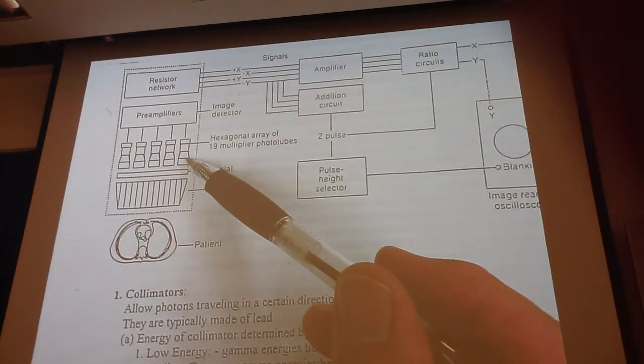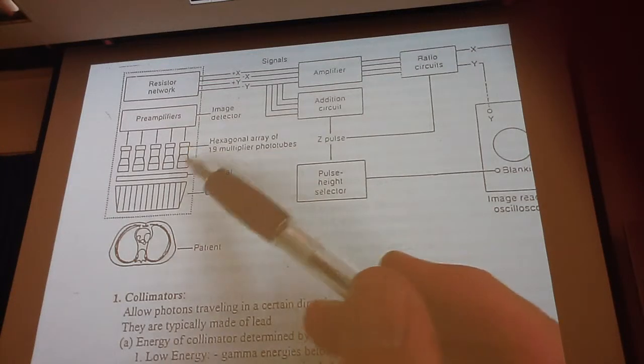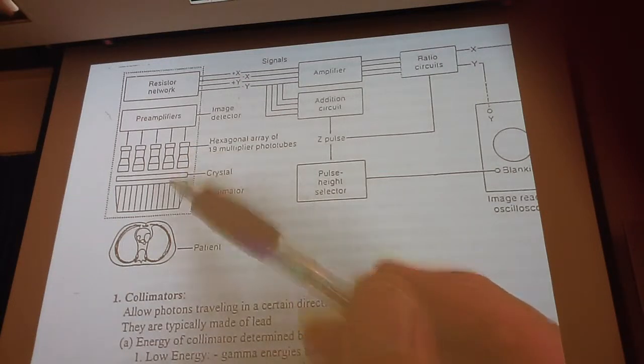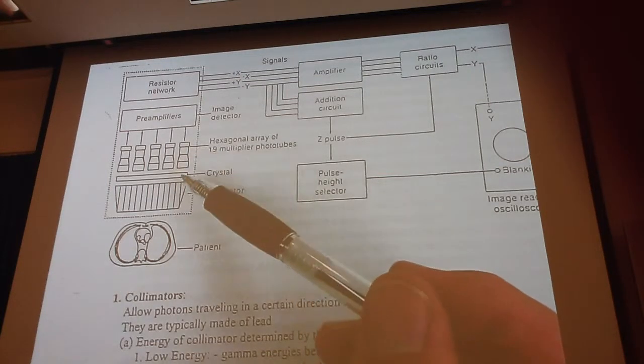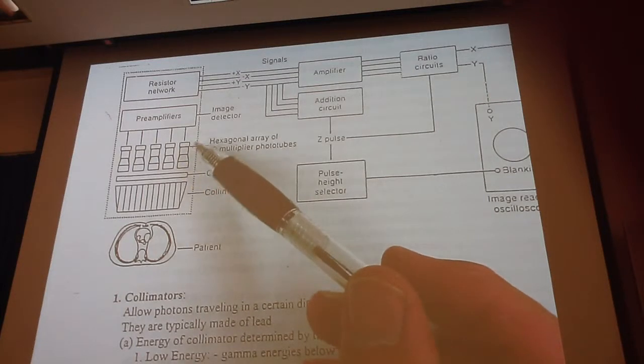They're called dynodes. Remember, there's anywhere from 10 to 12 dynodes, and each time an electron hits a dynode, it knocks off more electrons, and those more electrons are accelerated to the next dynode where they knock off more. It's kind of like an old AT&T commercial, where you call a friend and they call their friends, and pretty soon everybody in the whole United States is using AT&T. You guys remember that commercial? It's kind of like an avalanche effect.